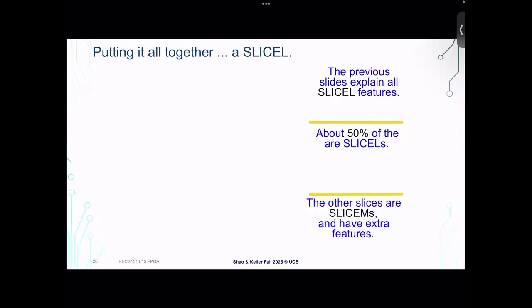Yeah, right. So an 8 LUT would need how many state elements? 2 to the 8th, which is big. It's 256. But if you build it out of 5 LUTs, you still end up needing the same number of state elements, right? It's just built out of smaller pieces. So it's not actually saving you any state.